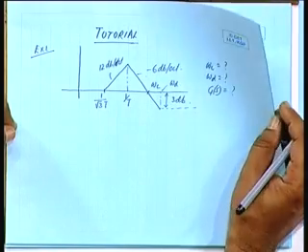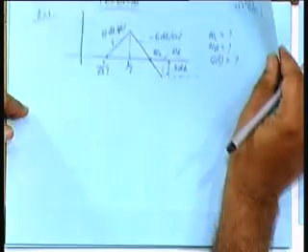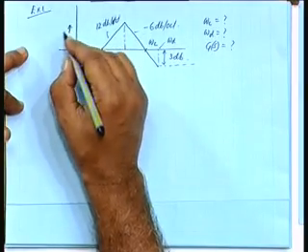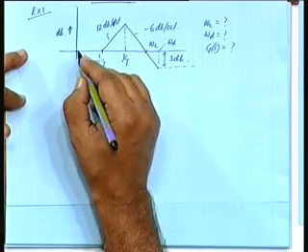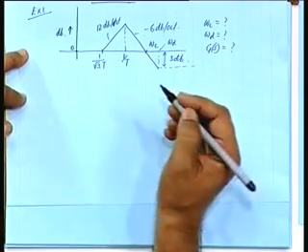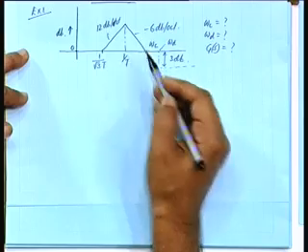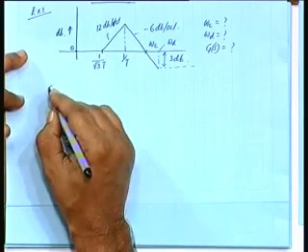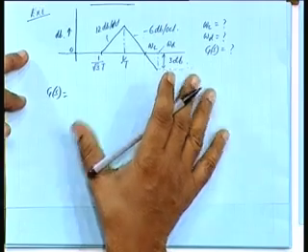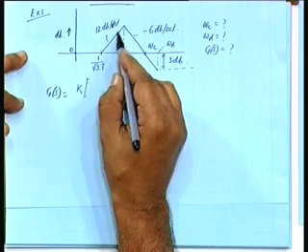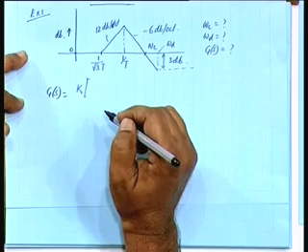Okay. So, for this problem, this is the dB gain, this is the 0 dB line. So, could you suggest the function like Gs, what it would be like? Gs will be some constant times, it is a slope going up at this frequency.